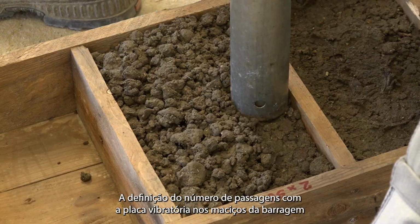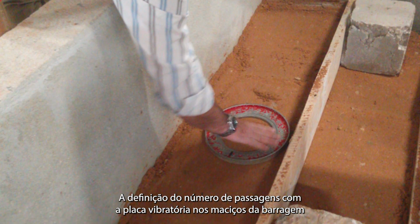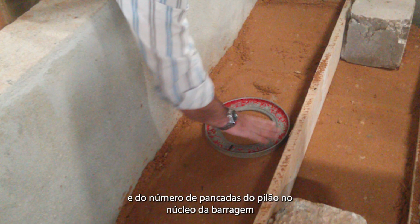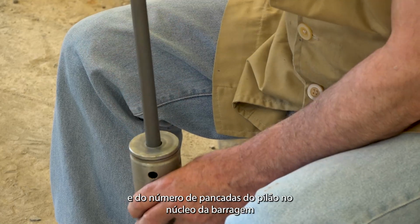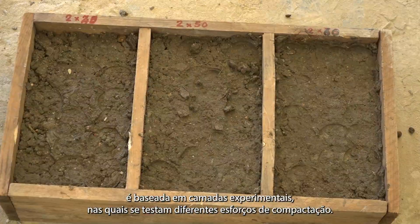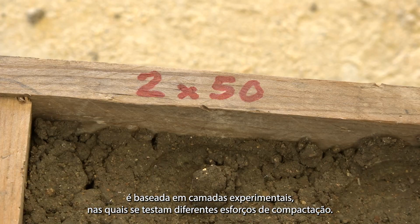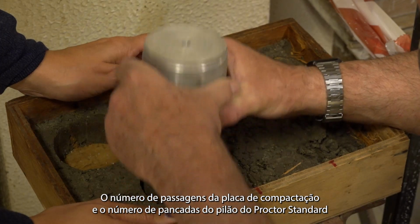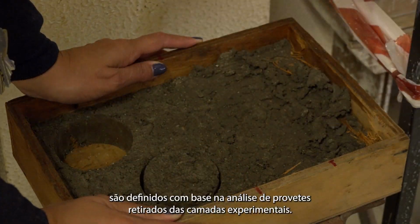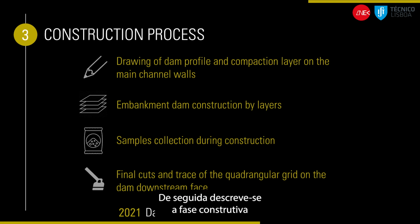To define the number of passages with the vibratory plate in the dam slopes and the number of drops of the Proctor test hammer in the dam core, different compaction efforts are performed on 2 layers trial lifts. Cores taken from these lifts are analysed to determine the adequate number of passages or drops. We now describe the construction phase.